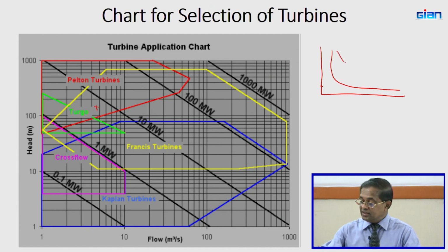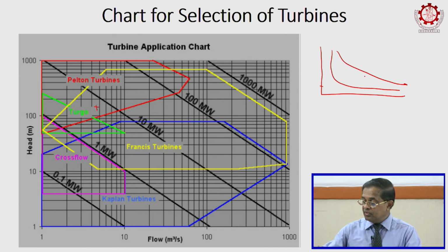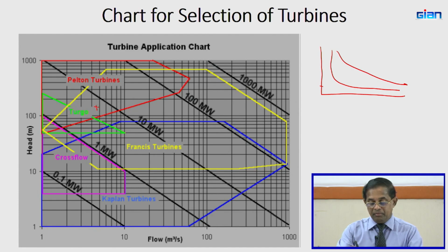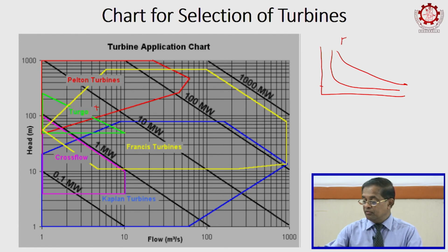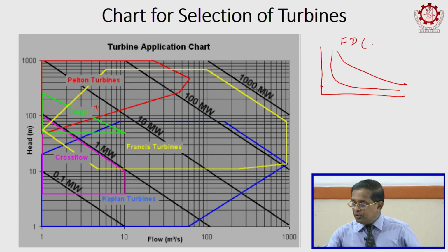But if it is like this, right, it is different, right. You have a lot of part load conditions, therefore, you must consider a Pelton machine, right. Therefore, when you have multi machine options available, you must look at the shape of the flow duration curve, right, flow duration curve. Now, why does the flow duration curve have these shapes?